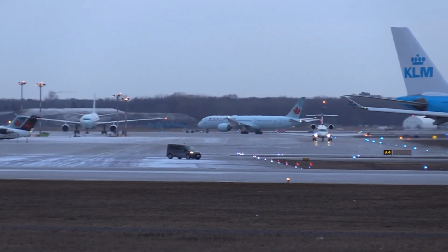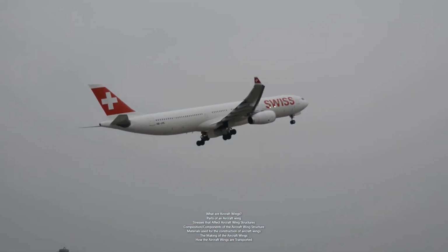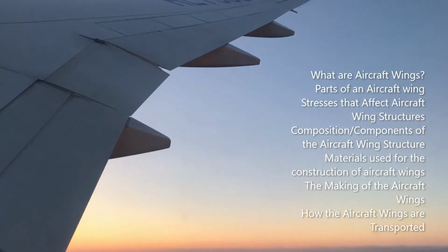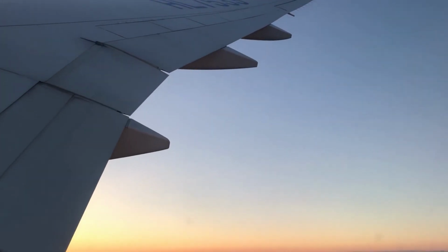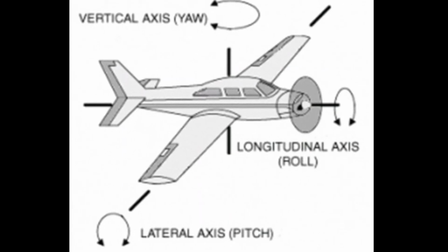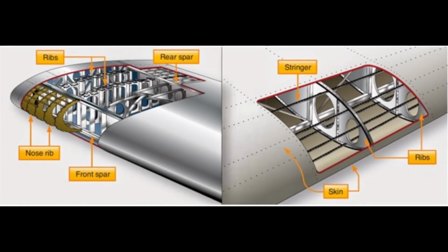When fuel tanks are not used, joints surrounding where the fuel is kept within the wing structure must be carefully sealed with fuel-resistant sealants. At the wing assembly line, the parts are added and tested before being sent to aircraft assembly facilities. Fasteners, rivets and bolts, are used in the making of wing structures. Their joints form key determining elements of the integrity of the wing frame.